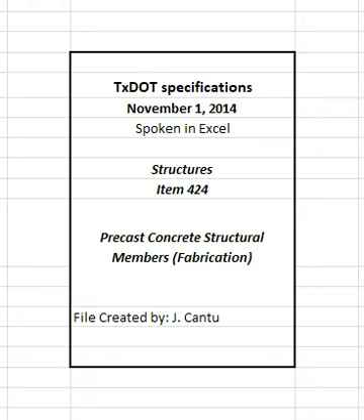4.2.1.2 Internal forms. Use solid expanded polystyrene conforming to ASTM C578 Type 1 for forming internal voids. The form material must be inert, non-biodegradable, non-absorptive, and strong enough to maintain sufficient rigidity to withstand the forces generated during concrete placement and consolidation without damage. Other materials for forming internal voids may be used when approved. Provide certification of conformance for void forms. The engineer may require samples to be submitted when needed.